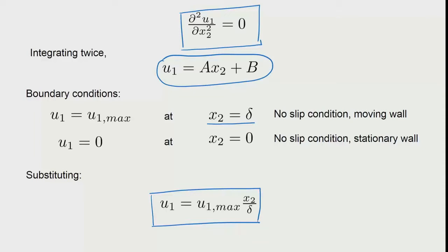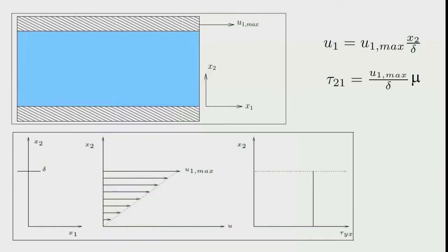So, this is a solution which gives you a straight line profile, which is the simplest profile that is possible for any solution of the Navier-Stokes equation. Okay. So, we see this plot, the plot actually shows you that it is a straight line. So, here I am marking the profile of the velocity u1 as a function of x2 or y.